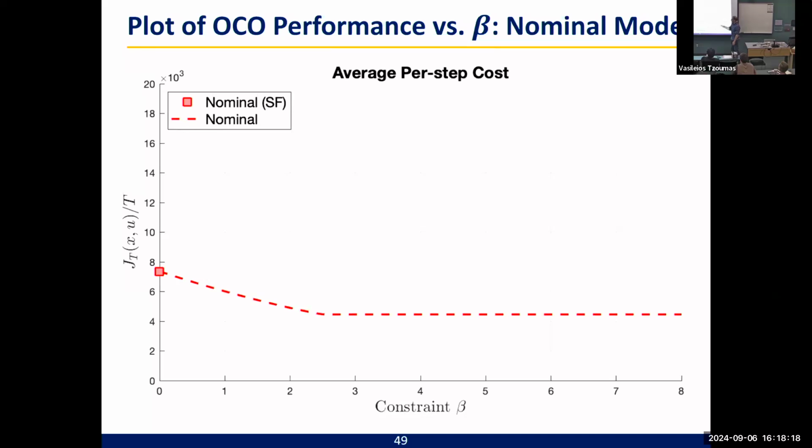I'm going to put a limit. I'll say what the outcome of our analysis was for a minute, but let's suppose I limit the output of their online convex optimization on this axis. So if I set the limit to 0, that means their online optimization isn't doing anything, and I get just the state feedback performance. So this is the average LQR cost on this vertical axis. If you allow their online convex optimization to work with kind of no limit or no bound, that would be going out in this direction, you get this performance. And everywhere in between, we've kind of filled in. There's no model error yet. Okay, so definitely their online optimization makes things better. Lower cost is better, so their online optimization does better than just doing the baseline state feedback.